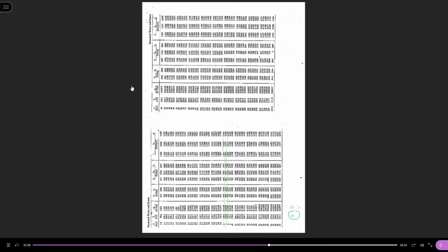So we know that state 2 is superheated. Also from here, we can find the specific entropy of dry saturated vapor and specific entropy of saturated liquid. In fact, by using the saturated water steam table, we can find all values on the saturation line.